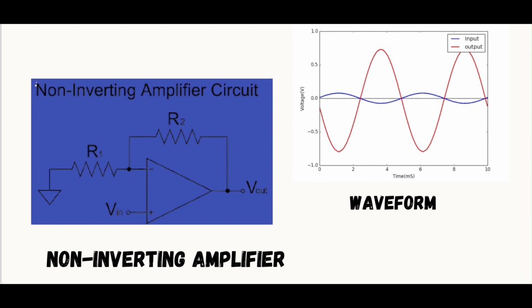Coming to the next, the inverting terminal, which is in negative form. The inverting terminal is basically not directly connected to the input. It receives the feedback from the output via the pair of resistors, as we know, R1 and R2. This feedback controls the gain of the amplifier and stabilizes the system. So from here the gain will be equal to 1 plus R2 by R1.